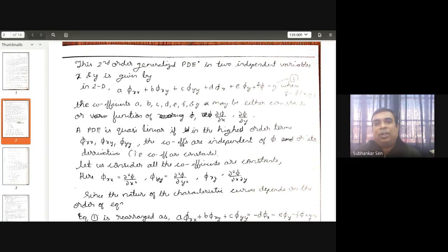So if a governing equation is of this format, what is the behavior of this equation? When we solve CFD problems, we have to know the mathematical behavior of the problem, that is, is it a marching problem, or is it a boundary or equilibrium problem? Is it an initial value problem or a boundary value problem? We shall decide based on the outcome of this equation. This outcome will help us to choose which kind of discretization we have to use for the governing equation.